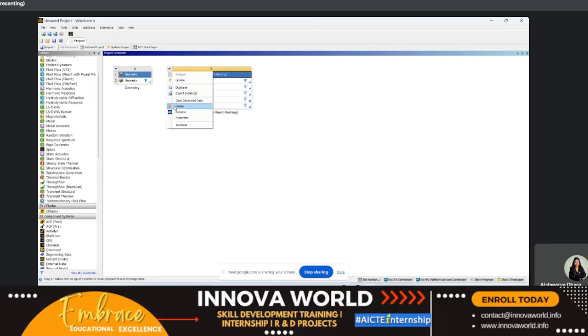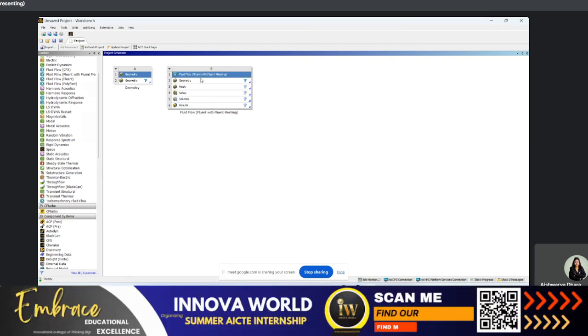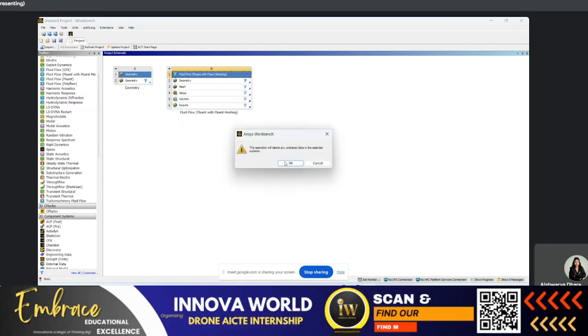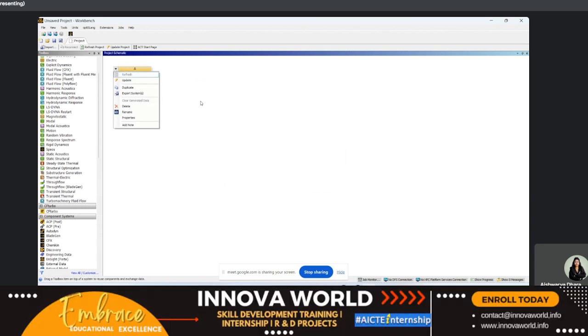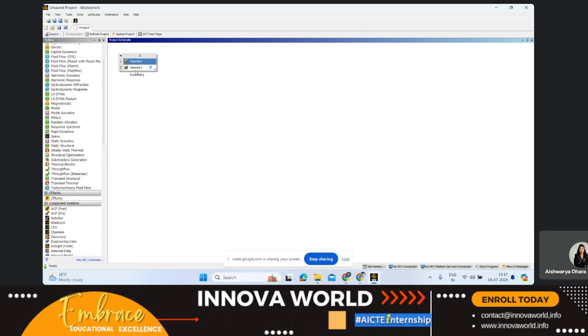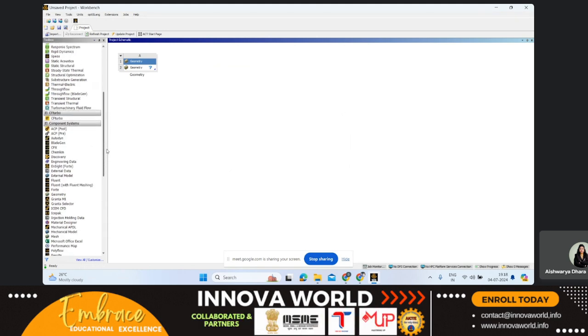Why? Because in Ansys sometimes some error will come, or some part will get stuck. In that case, if you are using the Fluid Flow module and any one part has an error, the whole thing we need to delete. No other way. But if you use separate Geometry and separate Meshing, you can straight away delete that part and restore the remaining things. Otherwise that cannot be restored.